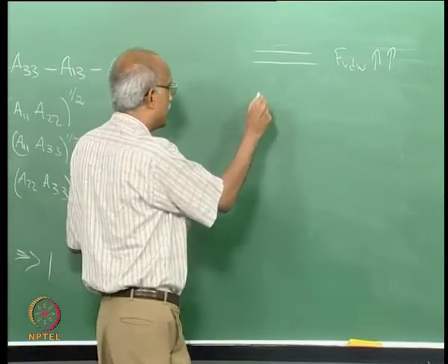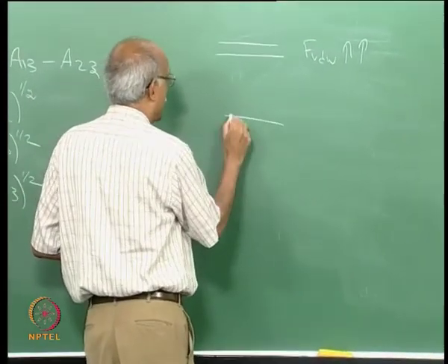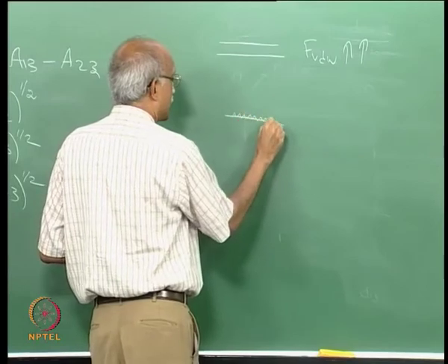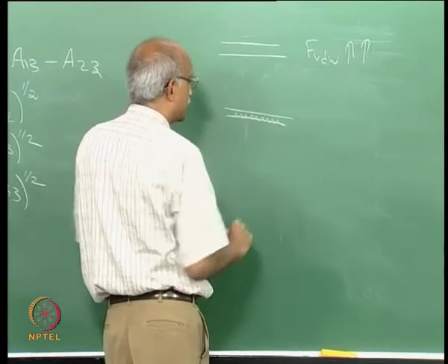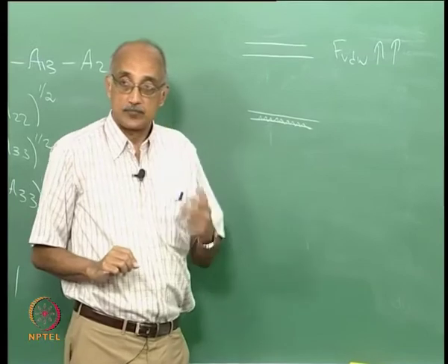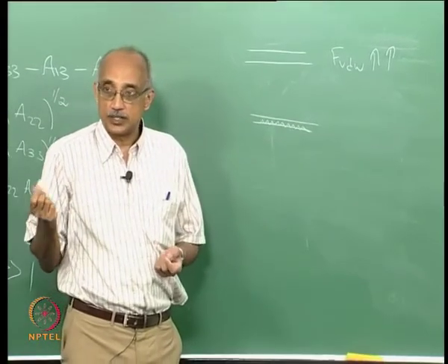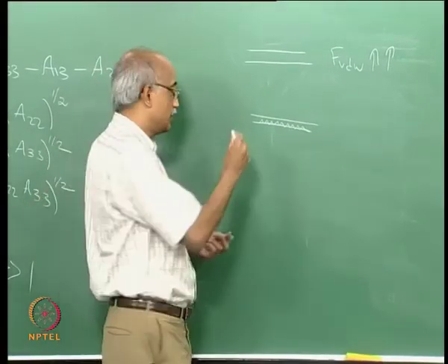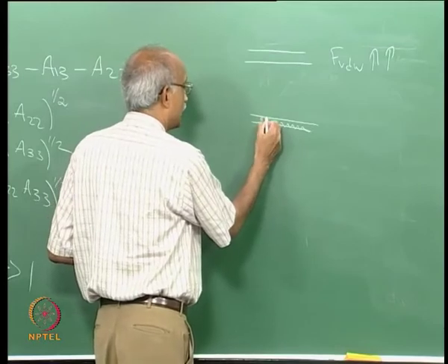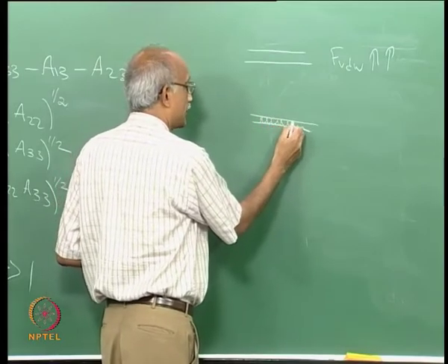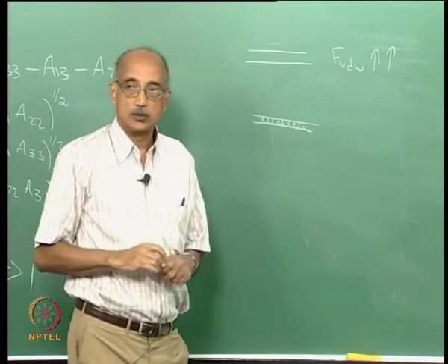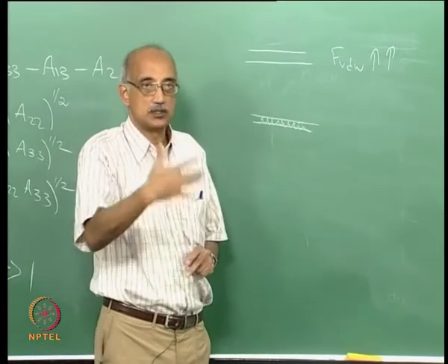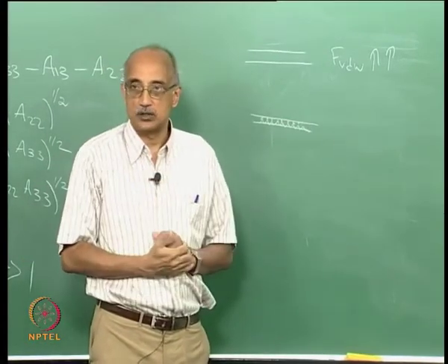But supposing now you roughen the bottom surface so that you introduce some asperity and now the top surface comes down, the forces are going to be reduced, right, because the effective area of contact is now only the peaks of the asperities, and so it virtually halves the area that is available for contact.